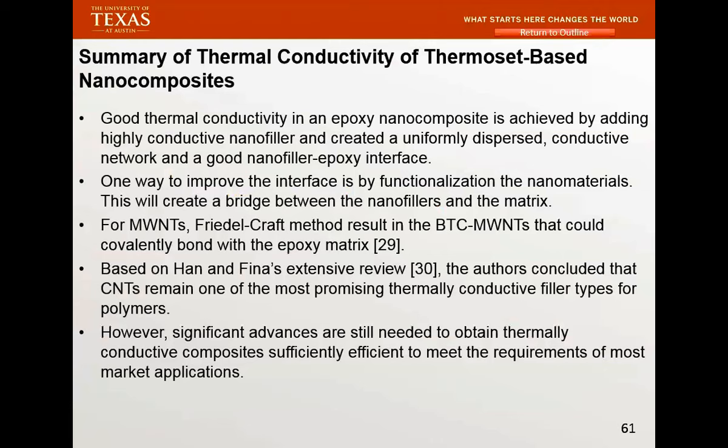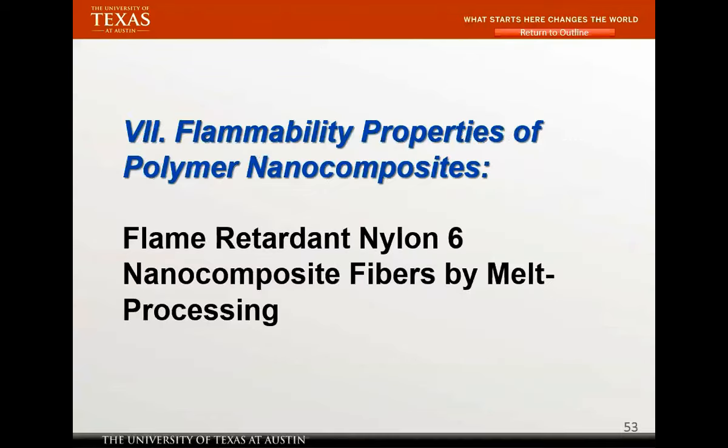Okay, I think one of the things that you also need to know later on is surface treatment. Unfortunately, surface treatment sometimes competes. Sometimes you actually hurt your thermal or electrical conductivity, but with surface treatment you always get better dispersion. So you have to see which is more important, and say this is what I want for my system. Okay, so that's what I want to tell you about thermal conductivity.